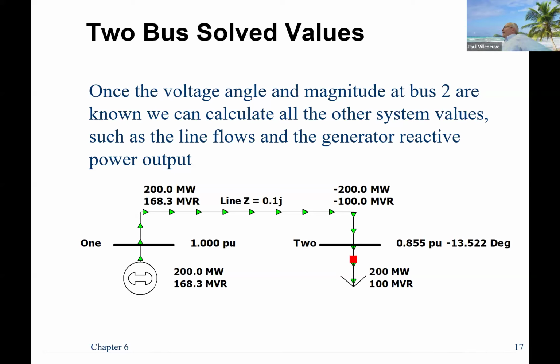So one of the things you do is like, hey, let's goose up the voltage. Instead of 1.00, let's see if we can go to 1.05. Does that improve things? This is such a simple system. Probably the easiest thing to do would be to like, you know what? I'm going to reduce the reactive power demand. So instead of 100 megavar, if I can drop that to 25 megavar by putting cap banks on that end, I can get much better voltages. So that's what the system operators do.